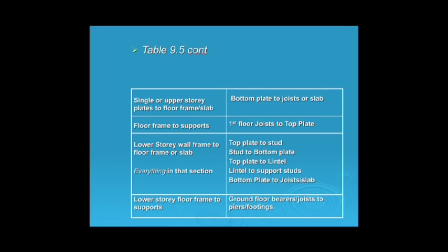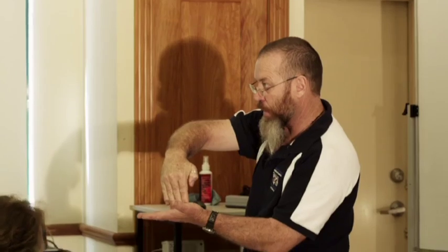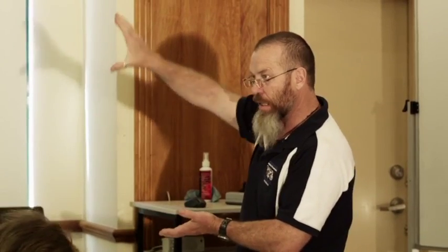So the first row is for battens. The second row is for all your roof connections, all your wall frame connections, right down to your stud bottom plate. So any connection that's being assessed in your wall frame or in your roof, you get the pressure from that second row through the building. Okay, that's what that description basically means. And I'm sorry, I haven't got any better way than explaining that to you.